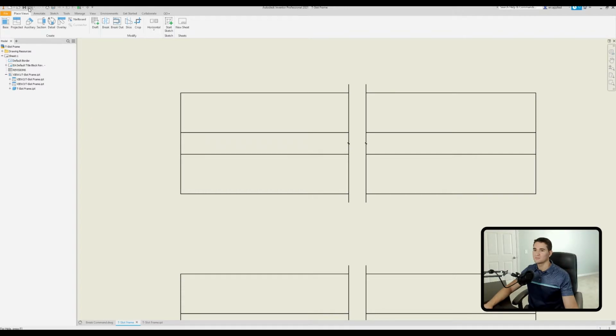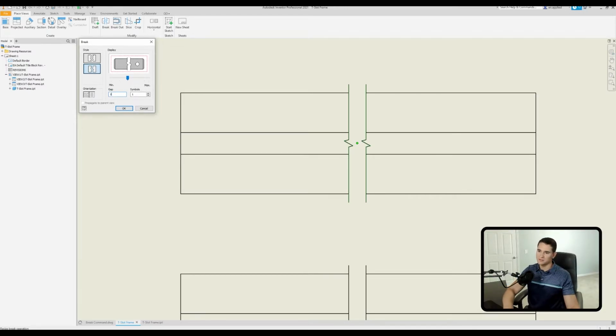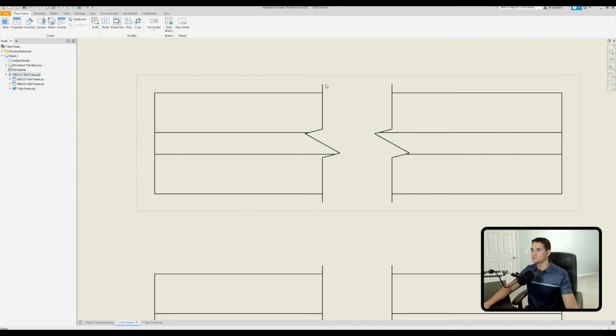Let's take a step back and go back into the menu once again. Let's set it to the maximum setting this time and click OK. As you can see there, the amplitude gets larger. Now let's take a look at the next setting, which is the gap setting. Currently it's set to the default of 1/4 inch. Let's set this to something larger, like 1 inch, and click OK. As you can see there, the gap goes to a measurement of 1 inch. That is the gap setting in the context of the structural style.